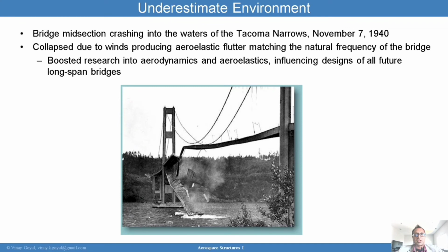Underestimating environments has occurred quite significantly. The bridge midsection crashing into the waters of the Tacoma Narrows, November 7, 1940, is an example of that. In this case, the structure collapsed due to the winds, producing an elastic flutter matching the natural frequency of the bridge.